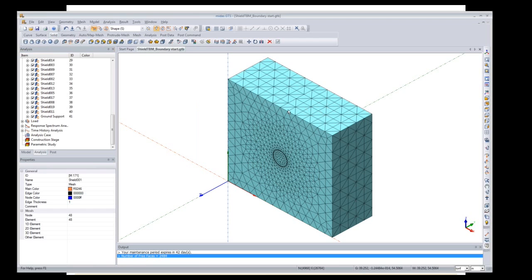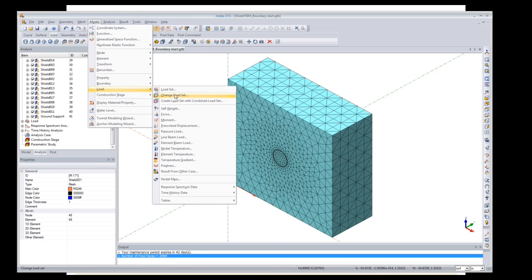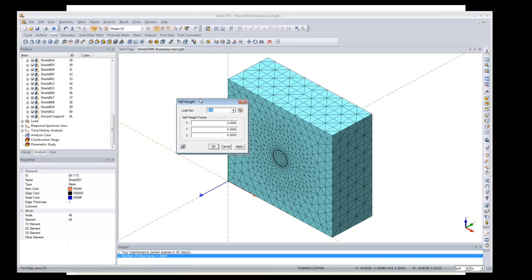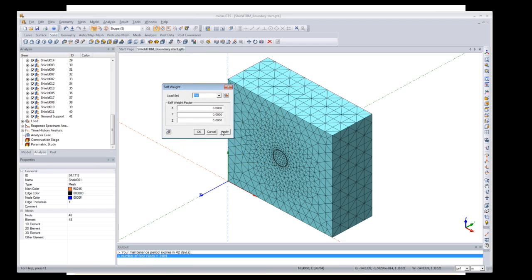In this way you can define the load set names easily, and I'll go to model, load, and then define a load for self-weight, which is SW here, and it will be applied in the gravitational direction, which is Z, and downwards, therefore -1. What the program will do is compute all the material properties and attributes, and apply the area of the member times the density, then multiply by -1 and apply it as the self-weight onto the structure.